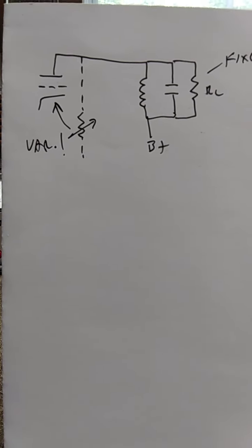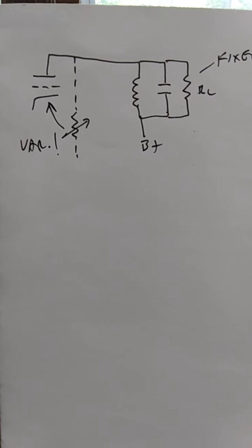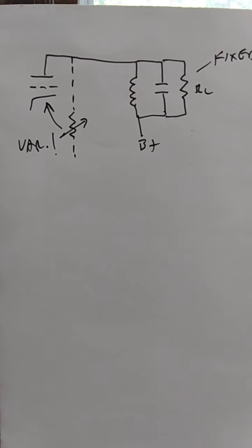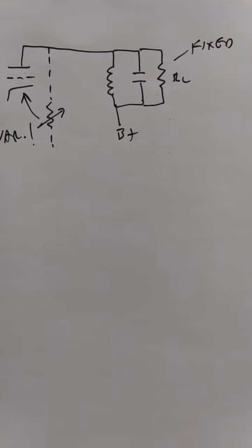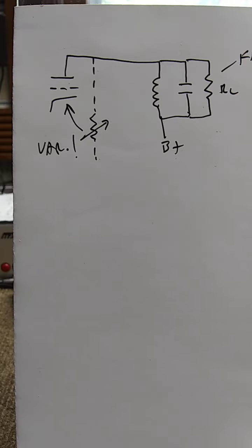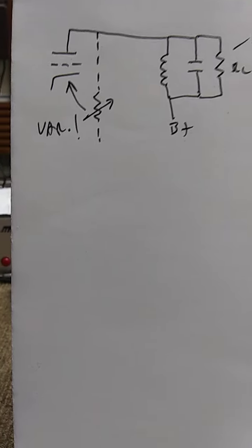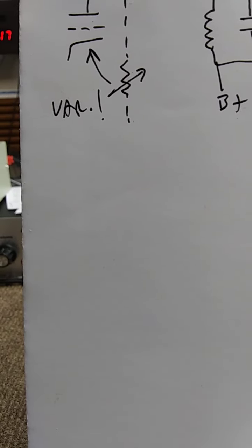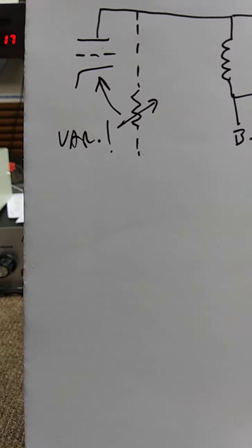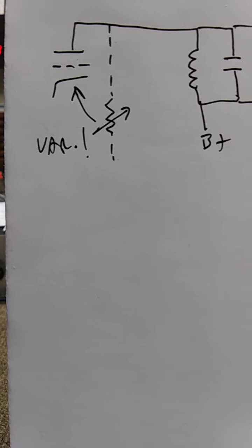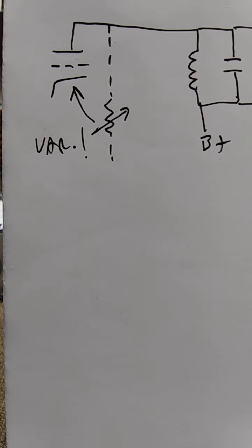What that circuit is, is this: taking plate current through the inductor in a parallel resonant tank at the operating frequency, whatever it is, fundamental, 2 or 3. When that parallel network is resonant, it essentially disappears and leaves a series fixed resistor. Well, obviously, in series with the tube. But notice the notation, variable. Notice the dashed line. That's representation of what the tube is doing. It's not obvious how we get there, but that's what it is.